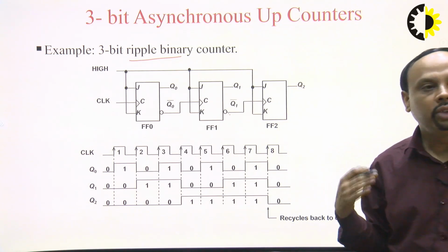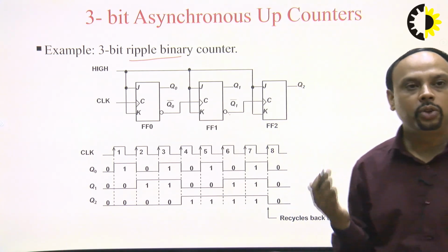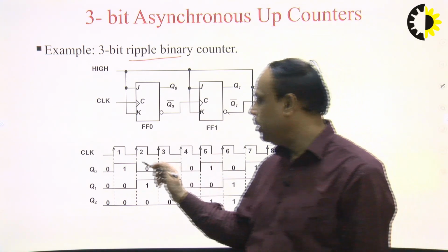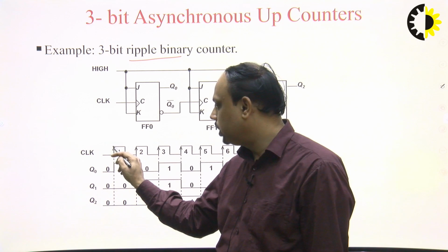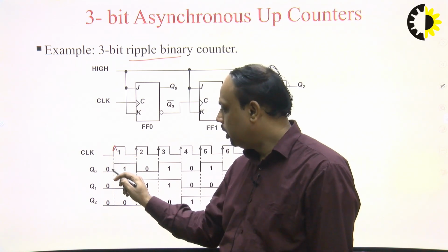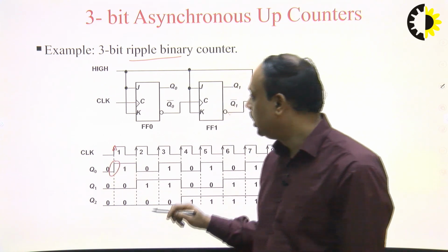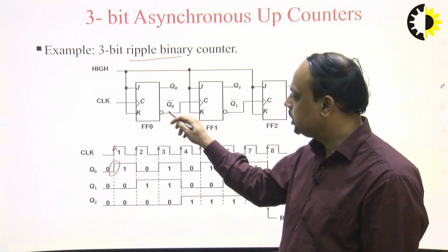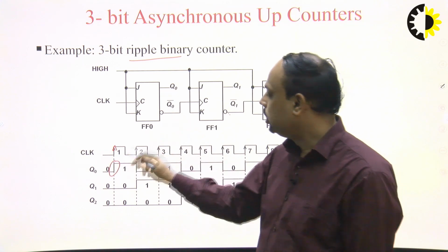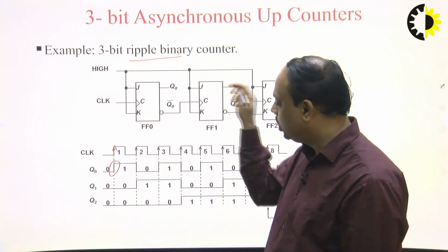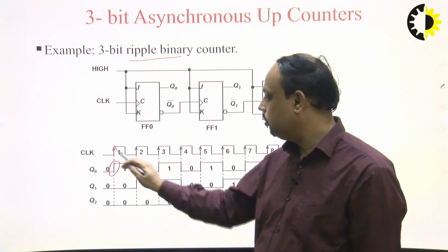So that's why these counters are relatively slow compared to synchronous counters. Again, the timing diagram is almost the same. The first leading edge comes, where flip-flop 1 changes its state, while the other does not change its state, as it is already at 0. And it triggers from 1 to 0, that is a negative edge that is coming, which is not over here.